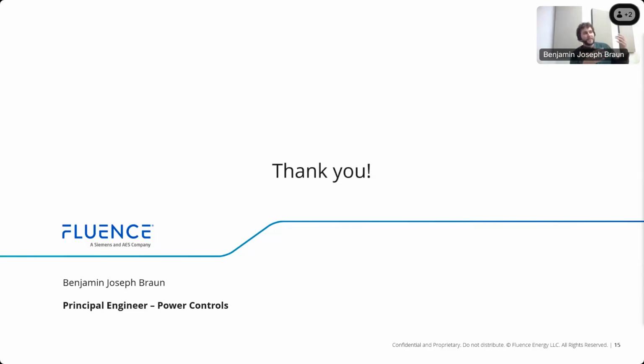Balance of plant, what I was talking about with metering, or if it's a Black Start project, with UPS and hardening your controls infrastructure. And then testing and validation. If we still don't have component standards, all of the testing falls back on the project developer, the solution provider. You have to do much more testing and validation up front, as I showed you what Fluence is doing. For national grid projects, we have extra tests proving the capability. Then on site, you have extra tests.